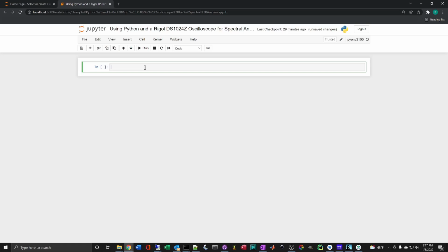Welcome. Today I will take you through the steps to control and download data from your Rigol DS1054Z oscilloscope using Python and a Jupyter notebook. This tutorial uses the DS1054Z library written by Philip Klaus. This library is required to replicate these examples in your environment.